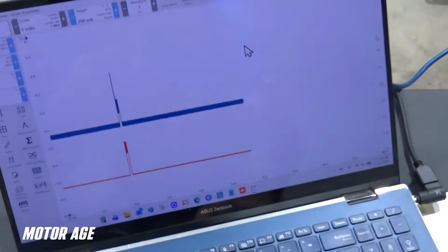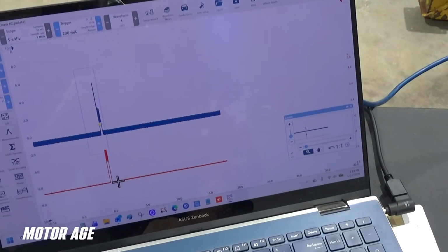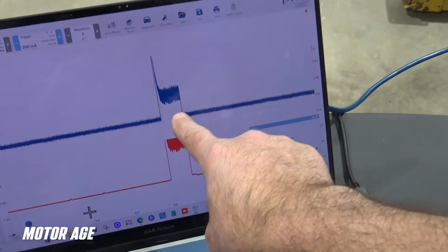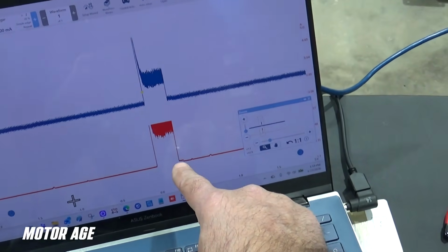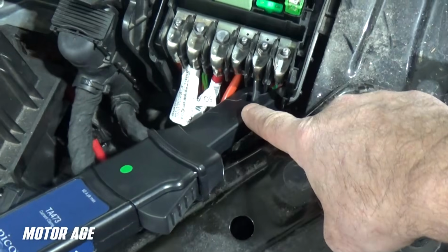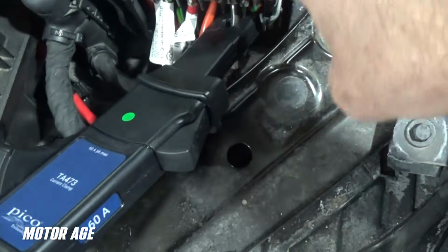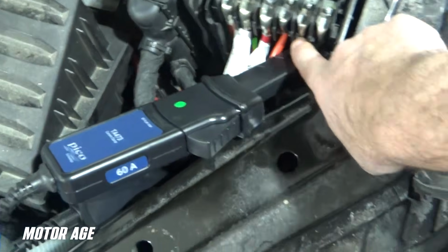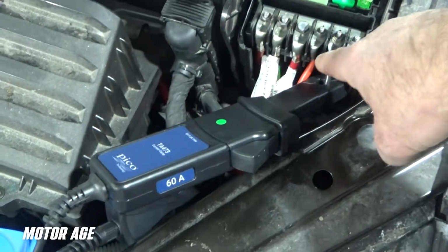So we got lucky. Here in this capture, I'll zoom in a little bit tighter and we will analyze this at our office later on. But channel A in blue is our primary amp probe, one indicating a problem is present, and our secondary amp probe is showing us current flow in the same circuit that we are referencing right now. So when current flows through the battery cable, through our primary current amp clamp, the secondary amp clamp here is showing current in this circuit as well. So instead of troubleshooting this entire vehicle via these 1, 2, 3, 4, 5 circuits, we only have to focus on this one right here, and we'll reference our wiring diagram and service information and see where it leads.